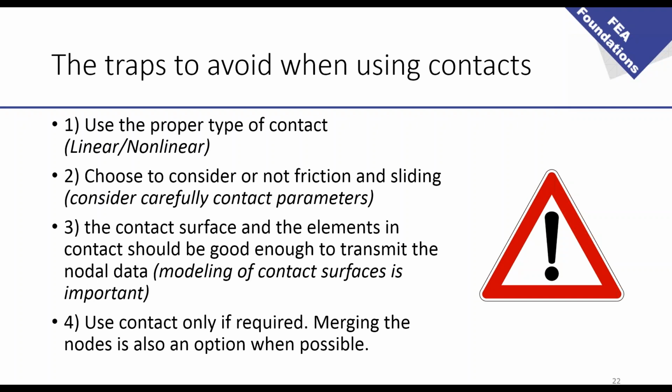The second thing is you have to consider whether or not to include friction and sliding, for example, and also your contact parameters. Contact parameters can have a big impact on your analysis, and you have to do some tests to see which parameter is working well, but you have some chance because in Midas NFX it's quite straightforward to do that relative to other software.